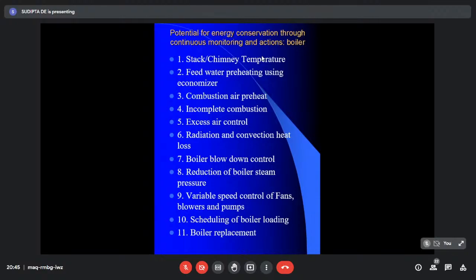And excess air means what? That excess air will be coming in at atmospheric temperature, so it will also carry away some heat. So automatically the excess air is required for better combustion, but at the same time reduces the heat availability, because the flue gas, the generated combustion products, temperature will be less. So engineers always have to make a compromise. So just write down. I'm not going to explain in detail how this excess air control is made. There are different options, stage combustions, etc. Those are advanced technology, advanced issues. I'm not going into those, but just write down.